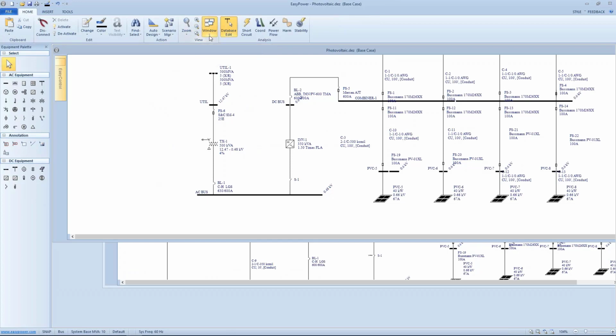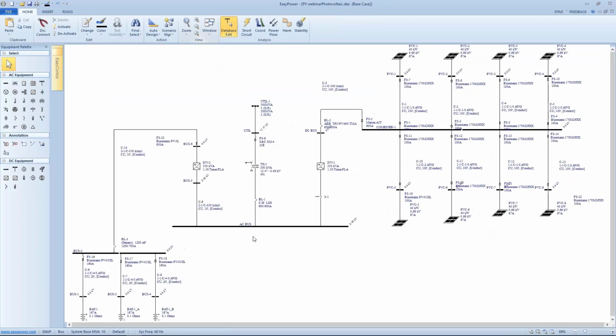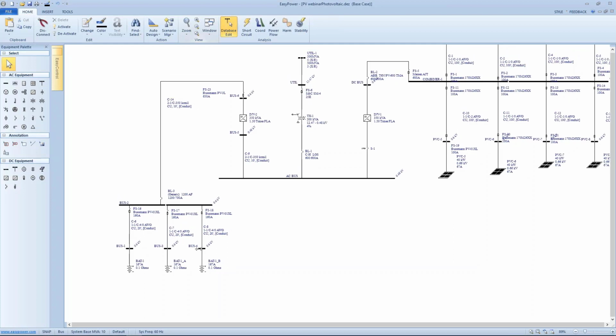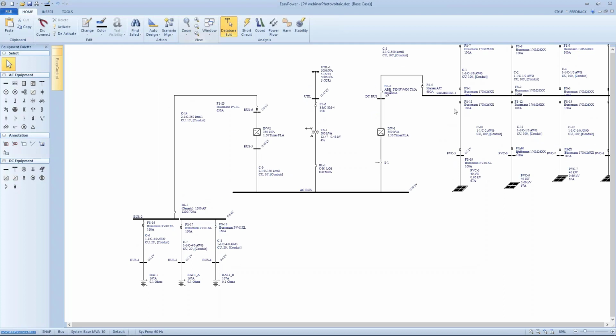And again, we have another example in the samples folder that has a DC link and a UPS battery backup system. So I've cut and pasted those batteries into an array over here. And this is where all of these rules start to have a greater import, because the fault currents are much higher in a battery system than you will see in individual arrays.